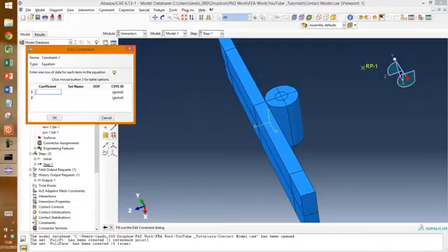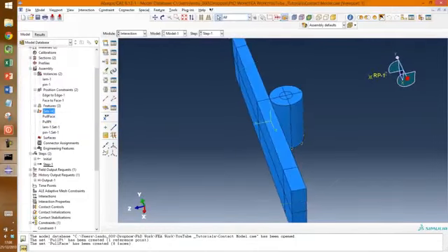So if you just type in -1 here and 1 here, this basically means, okay, well first I'll put in the pull face and then the pull point, and just put in 3 for degree of freedom. So basically what the -1 and the 1 define here is that everything that the pull point does, the pull face will do the exact same. If you had 1 and 1, the pull point and pull face would be doing the opposite thing, or inverted. So just accept that as it is. So we've defined that relationship.